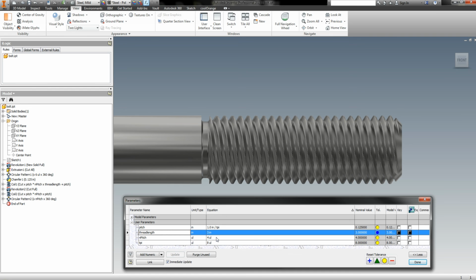To be honest, I have not tried that. I just know that you would have to cut away more material because otherwise you'd be size on size. Or depending on the accuracy of the printer, it might bind up because it's not perfect if you don't give it enough clearance. So you essentially just give it more clearance to make up for inaccuracy in printing. And yeah, I think that's really the main reason, because if you're drawing the threads to spec, then your internal and external should work out okay.